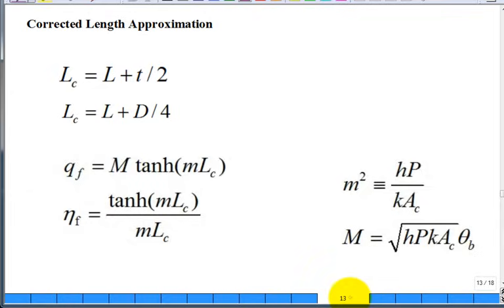Now, you say we use that very simple analysis for the insulated tip. We'll do this. As an engineer or budding engineer, this should really appeal to you. We know the physical length is this, but in our equations, treat the physical length as being extended a little bit, corrected. It's like taking that rectangular fin and extending it a little bit. How much?